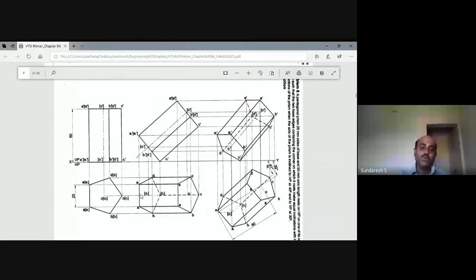The only thing you have to know is how we can satisfy the condition. So see this edge, what I am showing here, that is C1D1 or CD. When you project it back slightly towards the XY line, it should make 45 degrees. If you extend this line to the XY line, that is CD or C1D1, that should make an angle of 45 degrees with respect to HP.